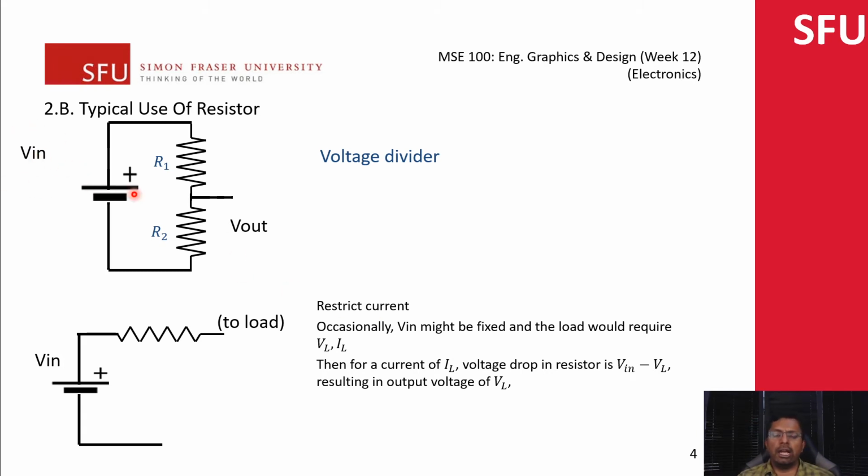This is known as Kirchhoff's voltage law. Essentially what it says is the total sum of all the voltages needs to add up to zero when you go through the loop. That means there is a voltage drop here and a voltage drop here. This is actually a voltage jump, or an increase in voltage. So it is going to be divided between these two resistances, R1 and R2, in the ratio of R1 to R2.